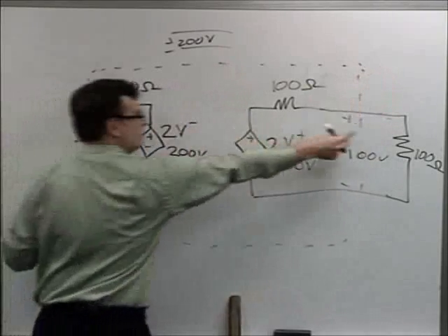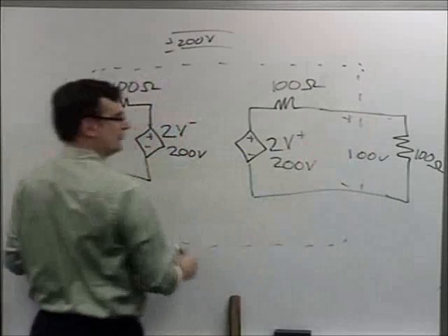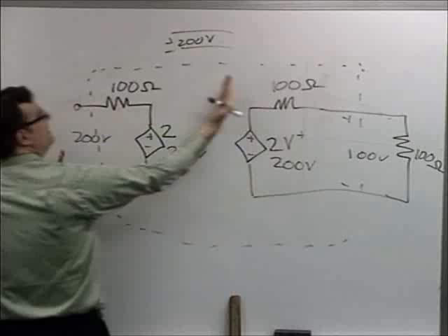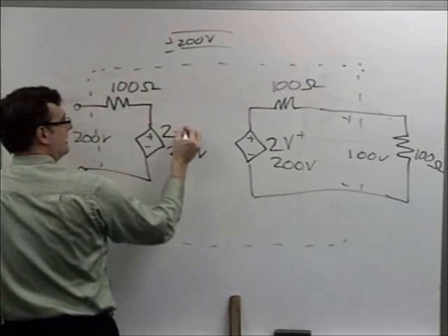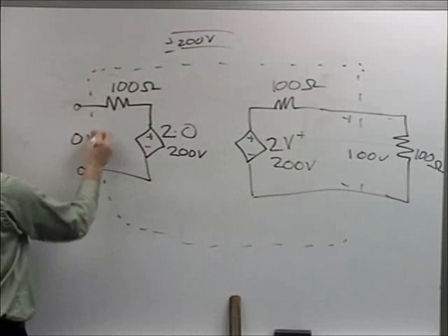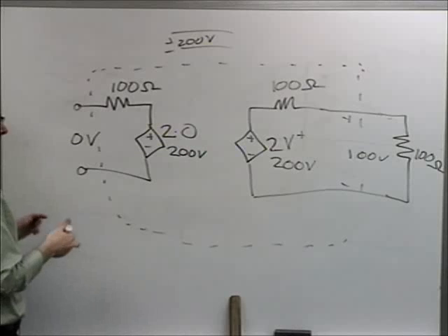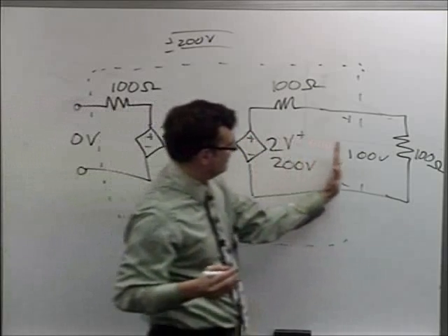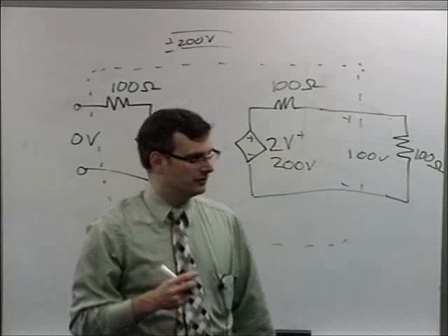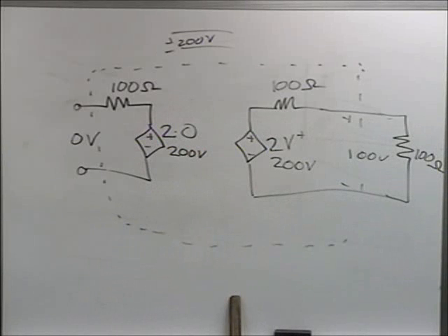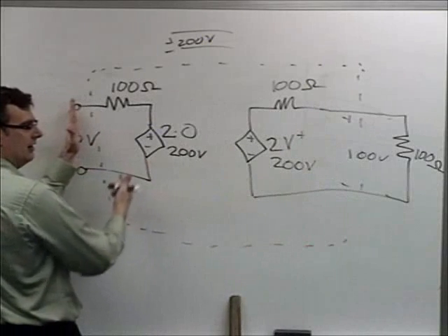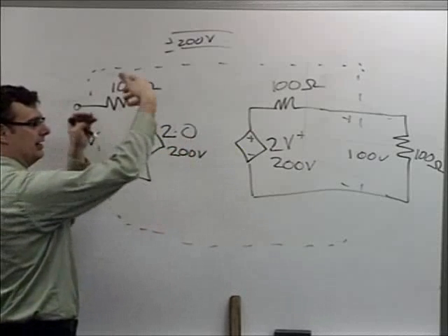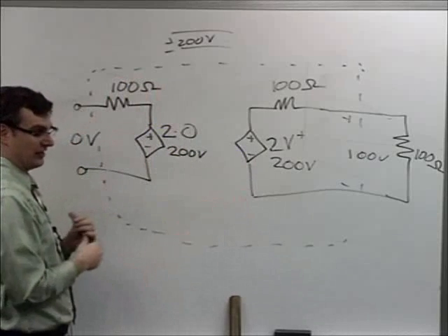Just be careful, because V minus has changed as observed from the front end of this line as soon as that finger touches. And eventually this becomes 0 when that reflection stops feeding the backwards propagating waveform after one transit time. So it becomes 2 times 0. 2 times 0 is 0 volts. And now, one transit time later, this side doesn't see any voltage. And the remainder of the 100 volts, no longer being fed by a reflection, wipes itself out and expends itself across the finger. What did you say? It's a negative 1 coefficient at the end. Well, no, it's a 0 reflection coefficient over here. Oh, yeah, you're right. Yeah, but and that looks like an erasure, right? It's basically a single forwards propagating waveform that is no longer being fed by any sort of source or reflection. Just turns itself off.